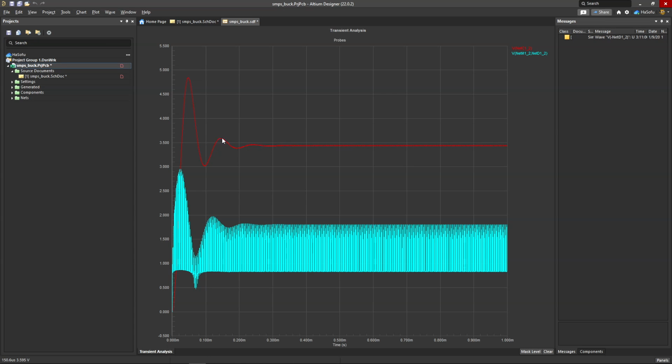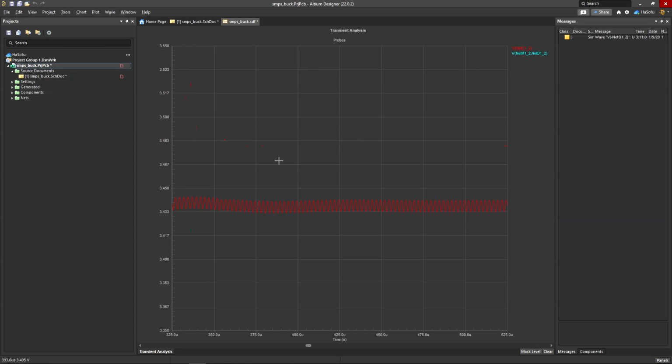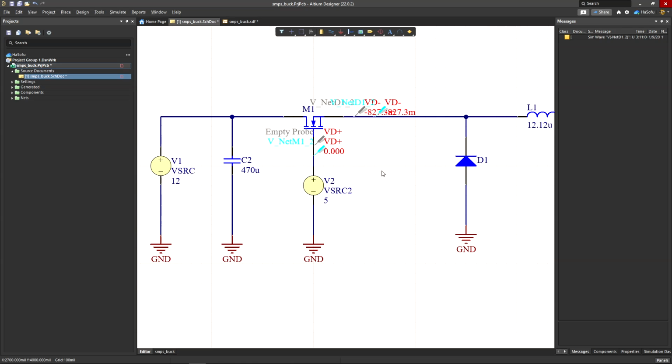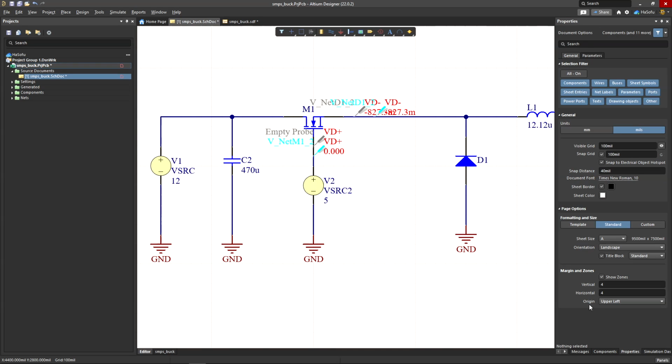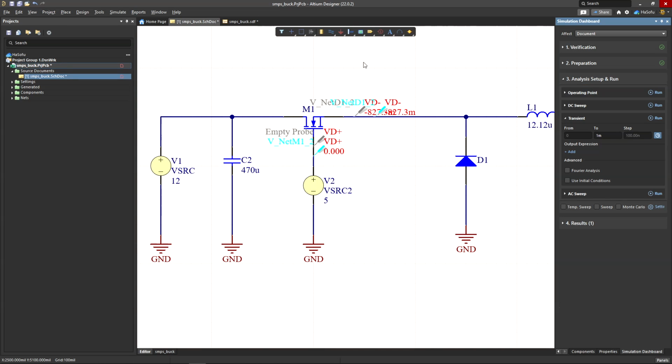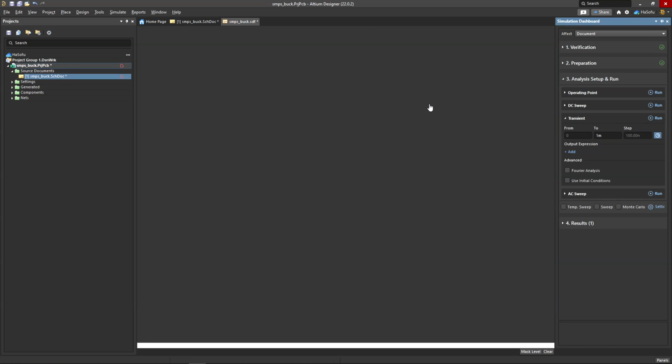So here, even at the 11 volt mark, it's still not quite at the 5 volts it needs to be. It's a full 1.5 volts lower on this output than we're needing. Let's go back in here, double click, set this to 12 volts, and then run this.